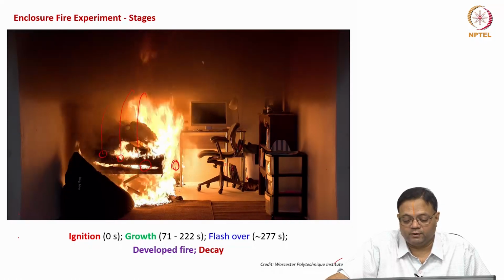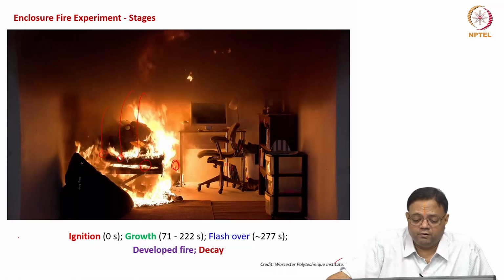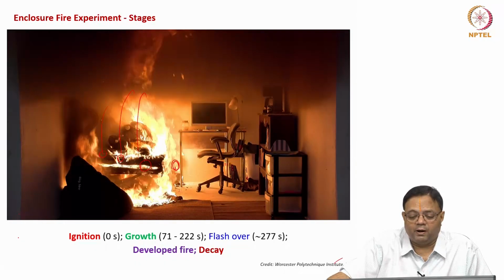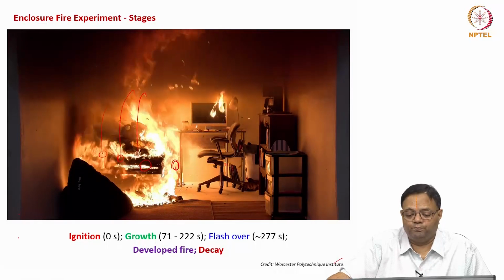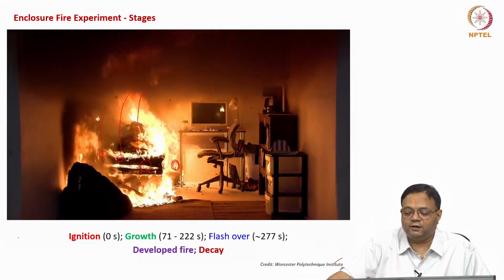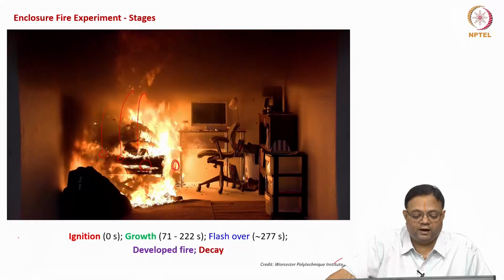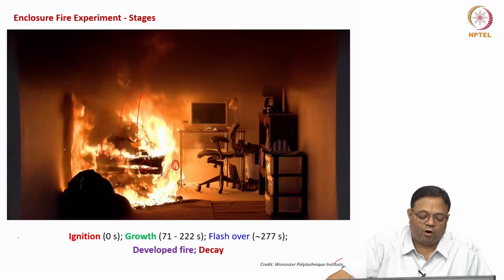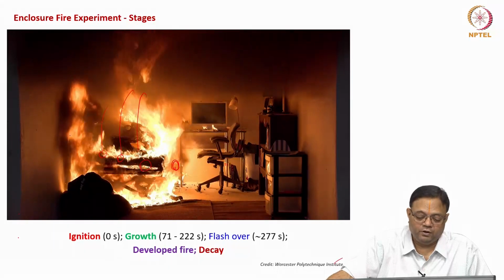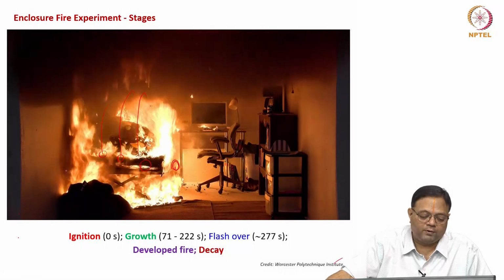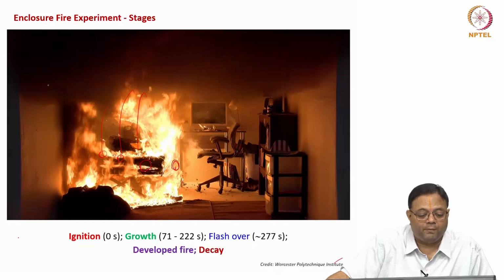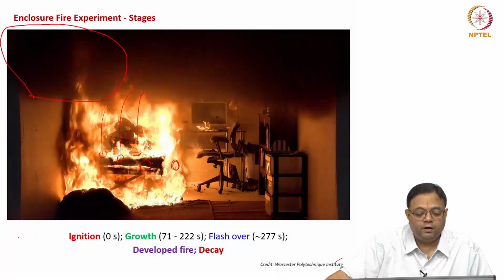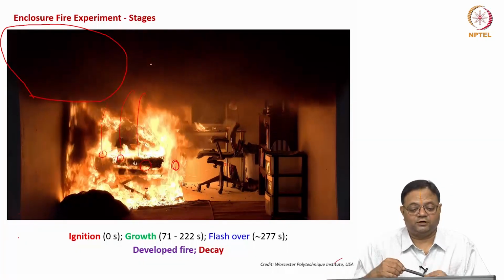One part of the table is completely ignited, and the burning nature of the fabric is such that it actually flows some burning particles over the room, and it falls over the other commodities. So you can see that here, since this fire is oriented towards the wall, you can see the wall effect here. So you can see a dark smoke coming out of the wall and a smoke layer going up, and you can see the descent of the smoke in this area, in this direction there.